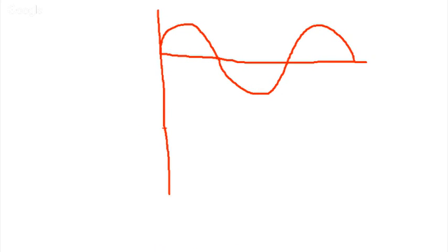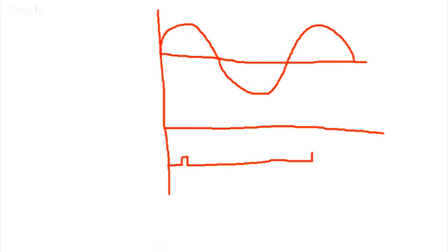Here we were first looking at 45 degrees. At 45 degrees, the first thyristors T1 and T4 are fired, and this firing pulse has to be repeated after 20 milliseconds. Here you will get a waveform, and similarly this waveform will repeat after 20. This is the positive half cycle, because during the positive half cycle only T1 and T4 are turned on. This is the firing pulse for T1 and T4.